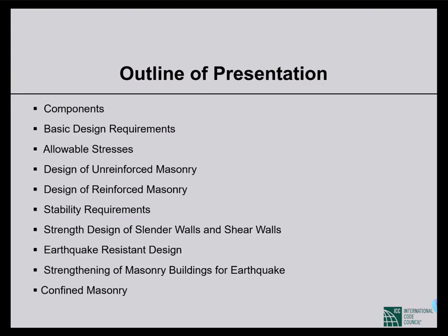Sometimes we can depend on the truss mechanism of the wall. That is, even if you take out a single brick, the wall doesn't fail because the stress is distributed by a truss mechanism. But if you want to take out a prism, then you have to first place a jack to take the load, number one.